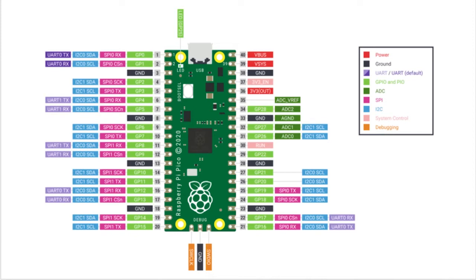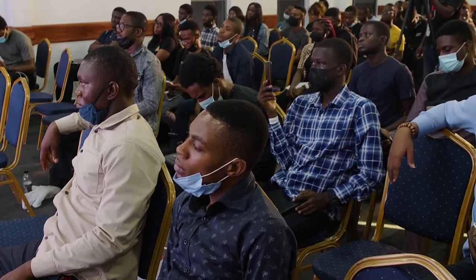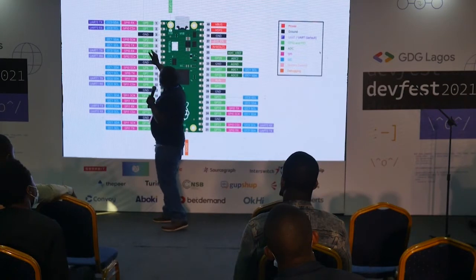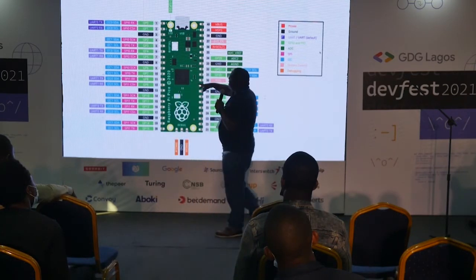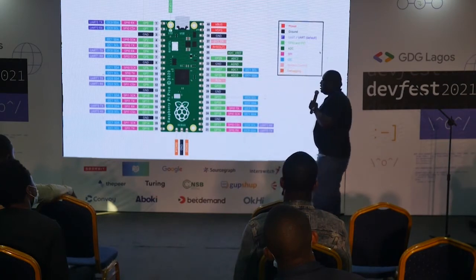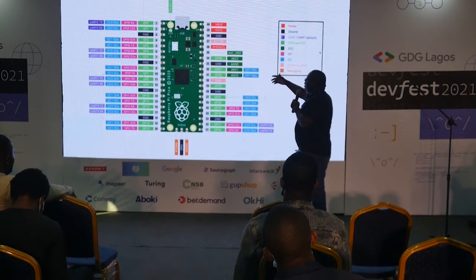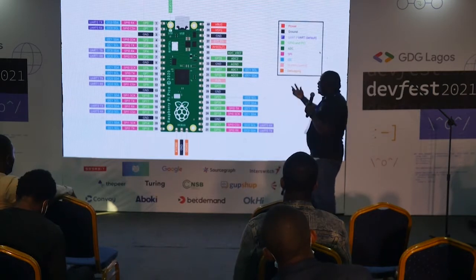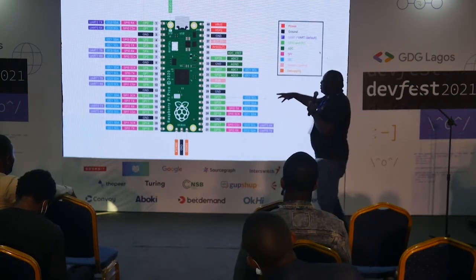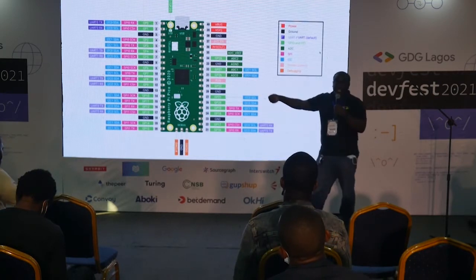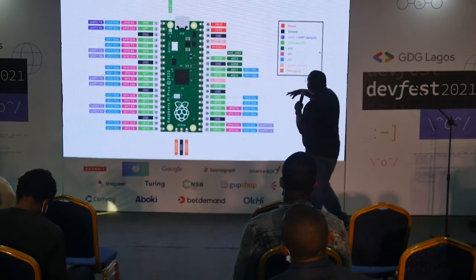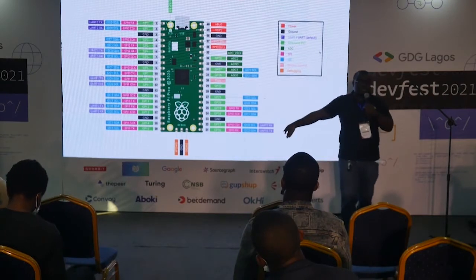The pins, depending on if you can see the colors, different colors have different meanings, right? This particular one is general purpose input and output. What it means is any green pin can be used for either input or output, general purpose. Black is ground or earth, right? So it's like you've got your power, so you can see power out here, and you've got your power in, where you'll connect your battery, your ground, because anything that is an electronic circuit must have power in and power out, right? The rest of it is color-coded, but that's what your microcontroller looks like.